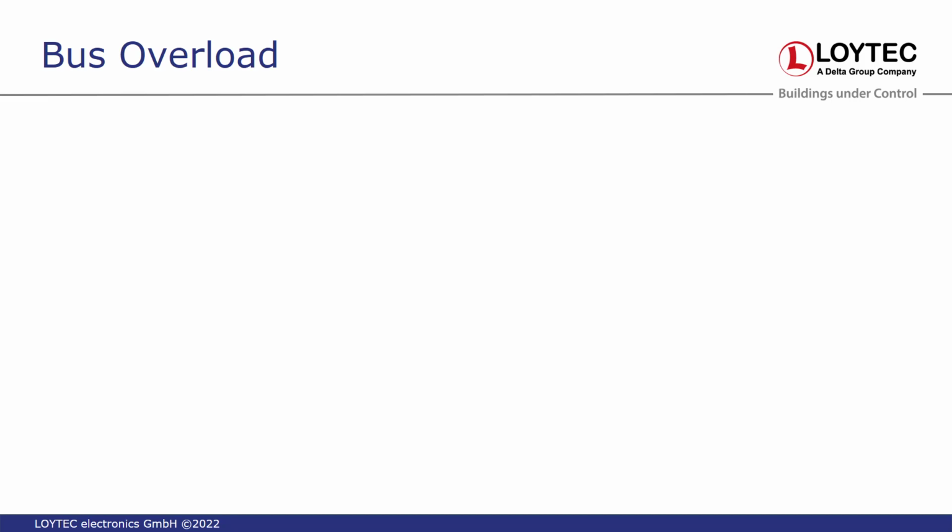So when you put more ballasts on the channel, you will have two issues. Either you're running out of power, then you will get a power failure, DALI supply power failure, or when you scan the bus, you will find fewer devices on the channel because you can just not assign more than 64. So these are two different things, but in any case, you can use a maximum of 64, maybe less, depending on the power supply and on the devices that you have. Yeah.